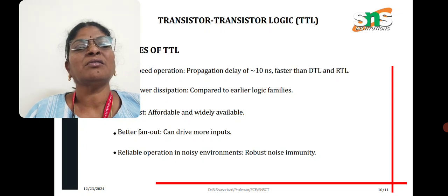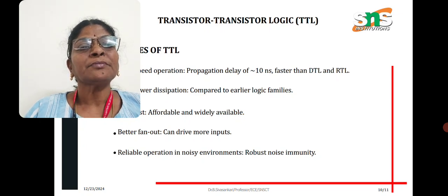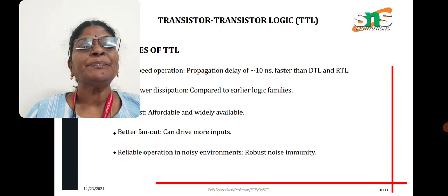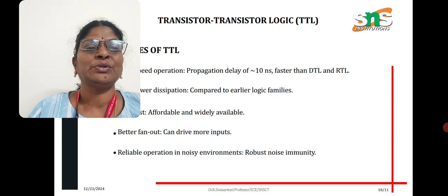So these are all about transistor logic and the advantages of transistor logic circuits. These are the advantages, like it has better fan out, can drive more inputs, reliable operation in noisy environments, robust noise immunity.